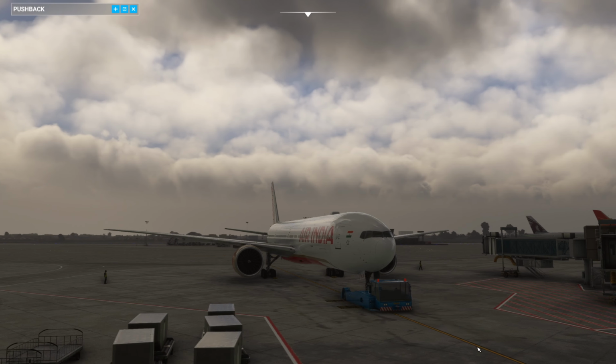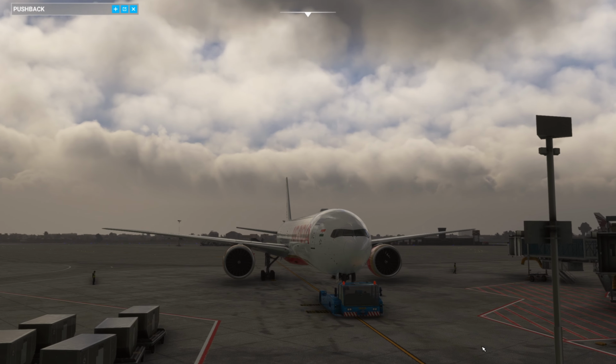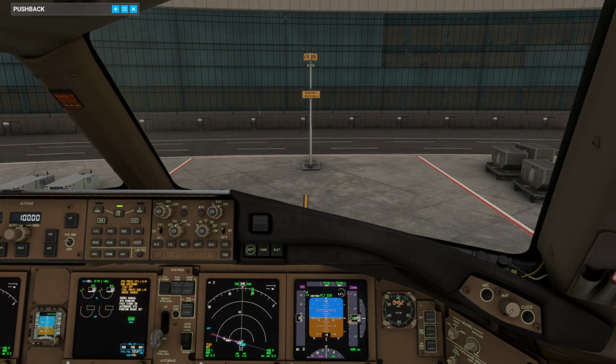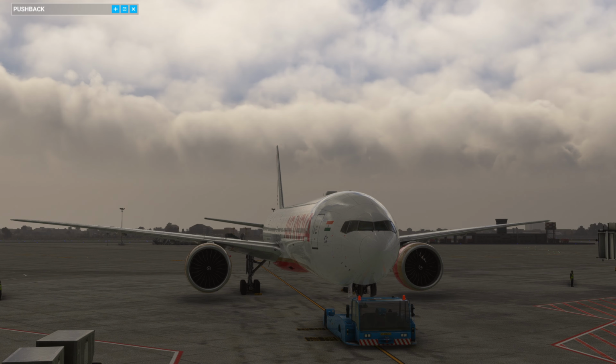Okay, sir. The bypass pin is installed. All doors and hatches closed and the ground equipment is removed. The parking brakes are set. You may lift. Parking brakes set. Lifting the aircraft.